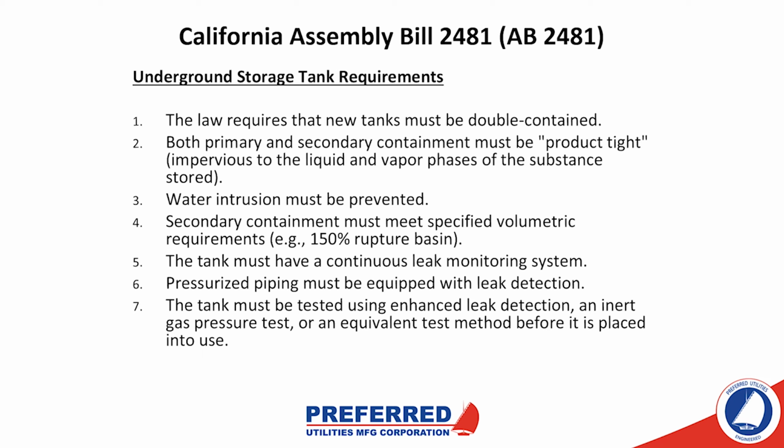That creates a situation where, by definition, the entire piping system is essentially pressurized all the way to, theoretically, the day tank. The only way to not have a quote-unquote pressurized piping system in a UST is to use positive displacement pumps placed above ground, and the underground piping portion is actually the suction line before the inlet of the pump set. And if that's the case, with a UST system, a different set of rules applies. And they're actually quite a bit simpler.